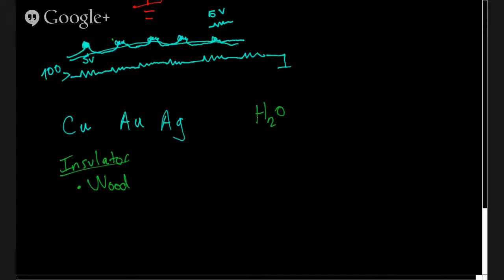Things that are less conductive than water: petrol, hydrocarbons, especially kerosene and alcohol. Those are very bad conductors, so bad, in fact, that if you have them in a container which can generate a static charge just from the flow of the alcohol or kerosene, then you do have a kaboom.